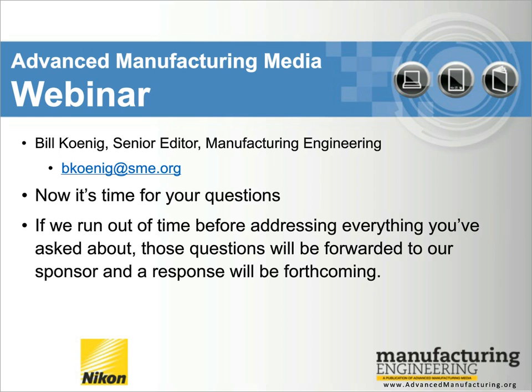CMM Manager is unique in that it has a direct interface to all of these different CMMs, controls the CMM directly, and you program directly in this package. PAS is simply an offline programming tool where you load a CAD model and create DMIS code. Then you take that DMIS code and put it into different software packages and typically massage that DMIS code a bit to make it work on that particular system. So the big difference is CMM Manager has a direct interface to this equipment and can be used immediately on an ARM or a CMM or whatever the target system is.